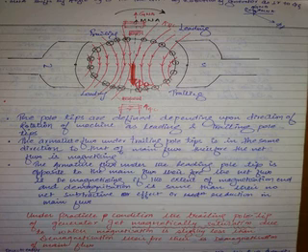Observe. Now, why you have defined like this, there's a reason for that. If you observe, the armature flux and the main flux under the trailing pole tips region, the flux density is increasing. There is a magnetization taking place under the trailing pole tips of the generator. Observe the diagram. You observe under one pole half, particularly the trailing pole tip. This trailing pole tip, that trailing pole tip. Under those two trailing pole tips, if you observe, the armature flux and the main flux are in the same direction. Yes or no?